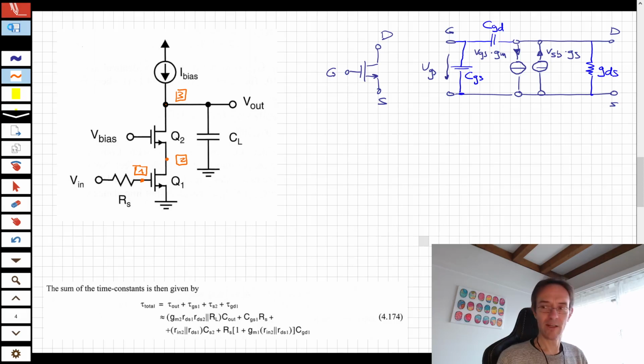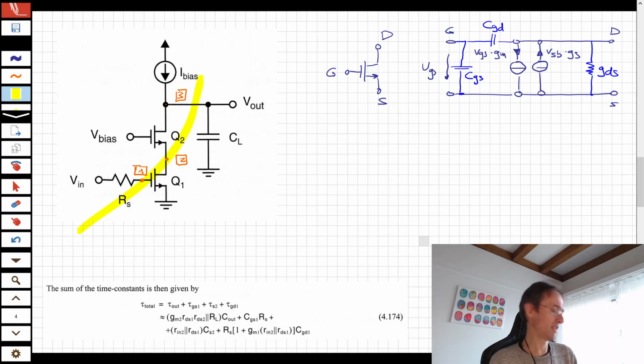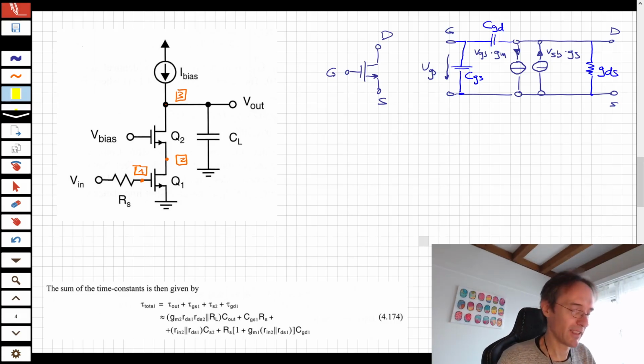So now I go over to the signal flow graph tool and I prepare a signal flow graph which has the same nodes here, and I will approximately use the same geometric configuration. So 1, 2, 3 should be rather vertical than horizontal. This comes from my thinking that if I do such a graph in the same way as I have the circuit, then I already know from the start that the graph will look relatively simple. So let me go over to the signal flow graph tool.